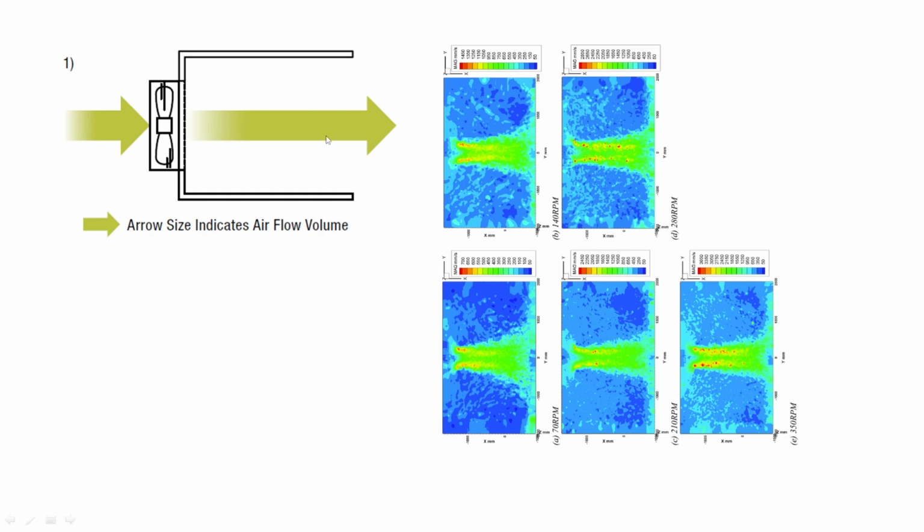CFM testing like this can be used, though, in a scientific sense. So you would generate a PQ curve, so pressure versus airspeed. You'd have some pressure sensors, you'd need an anemometer to measure the airspeed, and a variable size slit to then measure how well this fan operates in different types of pressure scenarios. That is perfectly valid, but saying this fan good, this fan bad for case airflow because it has big number traveling through a tube is incorrect.